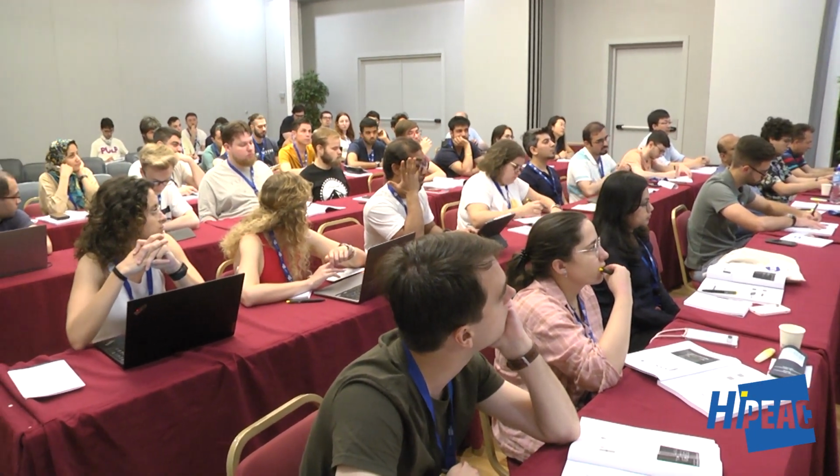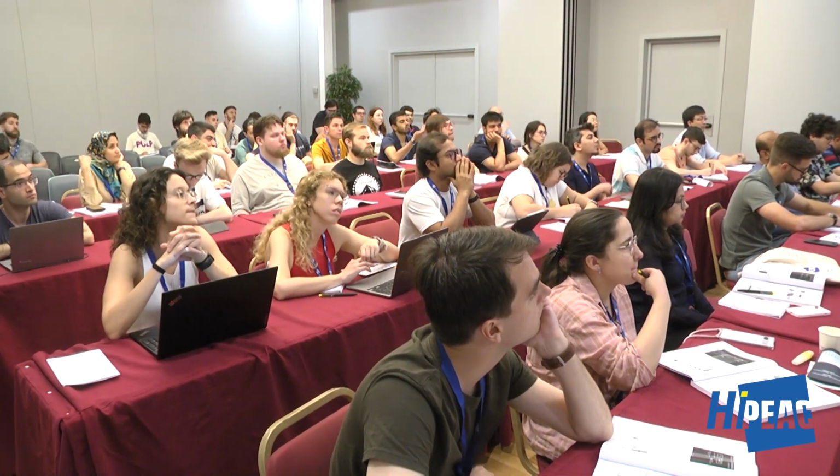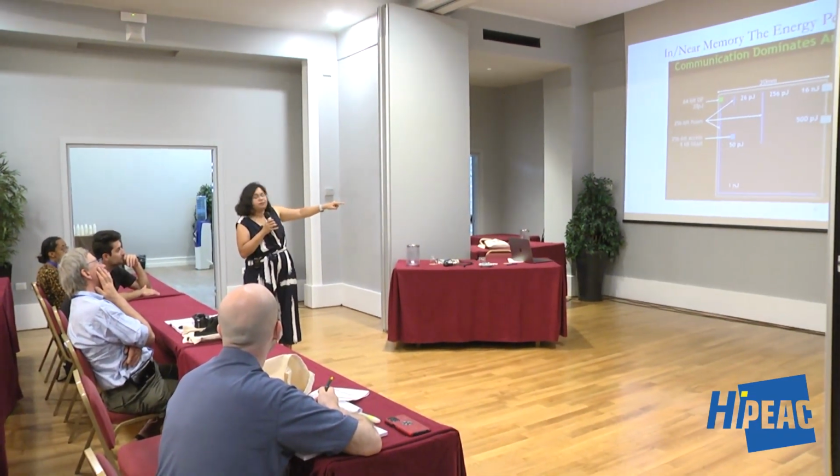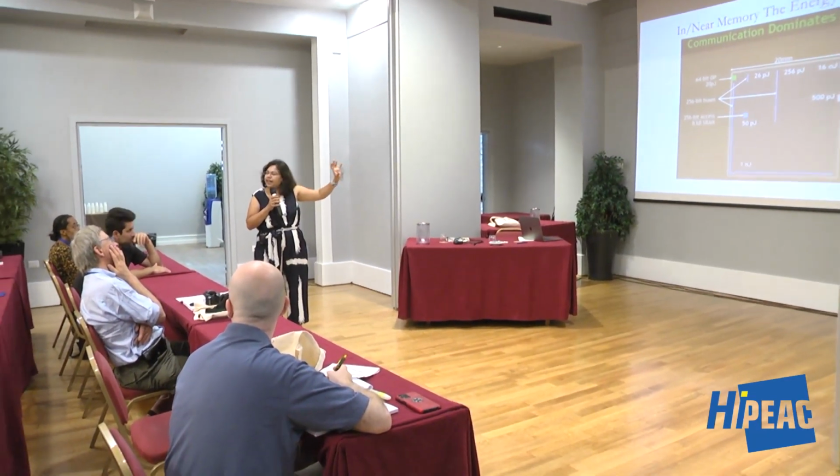Can you say what is the energy consumption of caches? Yeah, so SRAM is 50 picojoule here, right? But that's just one memory array. Cache would include the on-chip buses. So you're seeing these 256-bit buses, right? So you have to add that and the SRAM access to think about the total cache energy. Because you never just access one memory array.